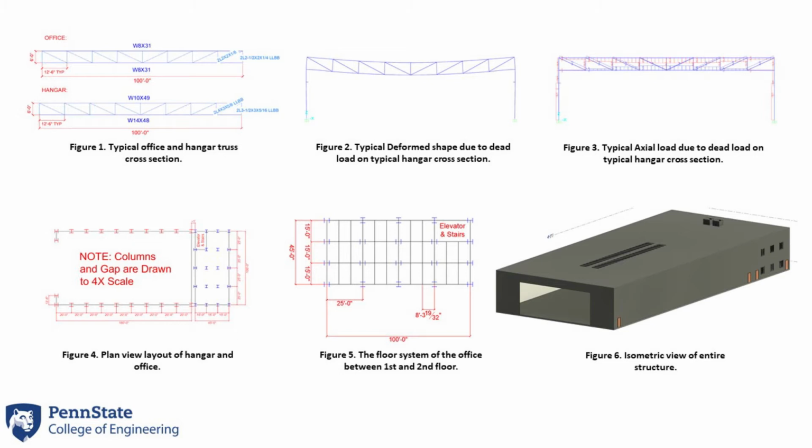In Phase 2, the team went forward with these designs to decide preliminary members and create a SAP 2000 model so that the system could be structurally analyzed. The use of SAP 2000 was extremely important as it allowed for a 3D model to be created and decreased analysis time and complexity of hand calculations.